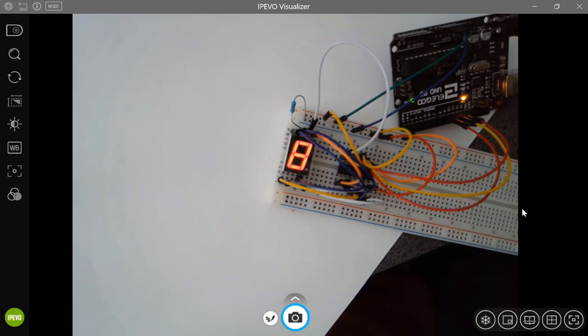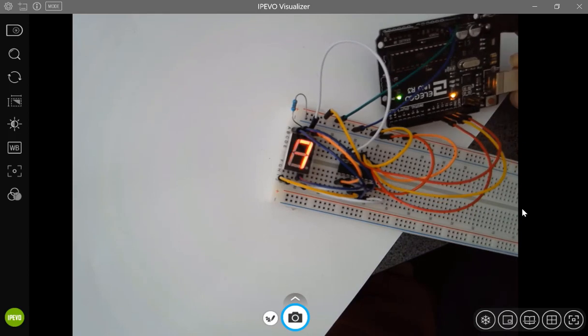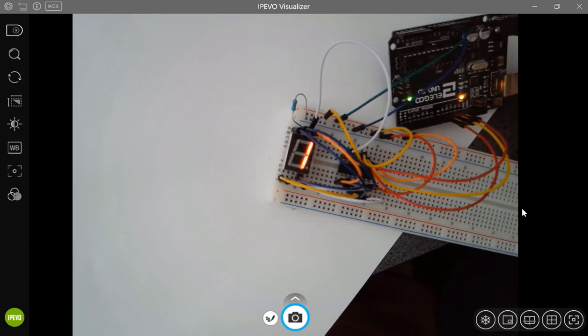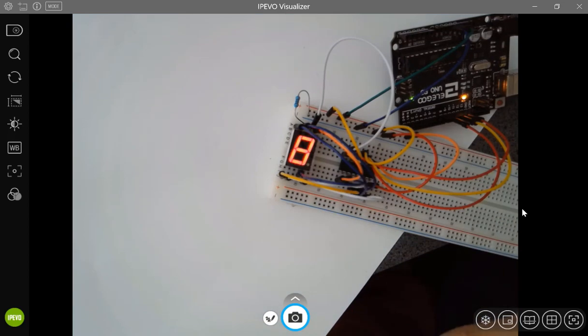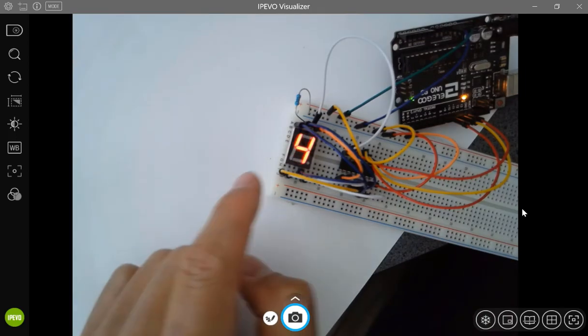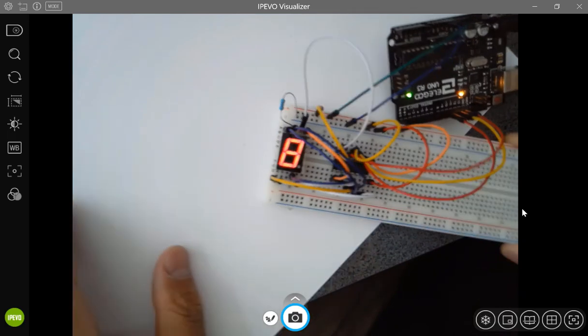If you have any other tasks for this CPU, like sensing temperature or scanning push buttons, you are not going to see a smooth display like this, because it's taking time to do something else. You do need a homogeneously distributed time delay between the different numbers for this kind of display.